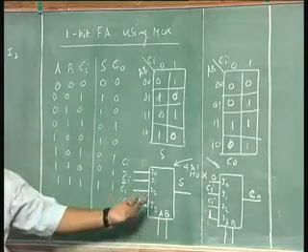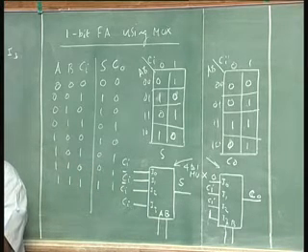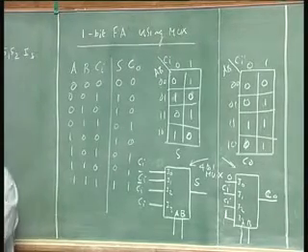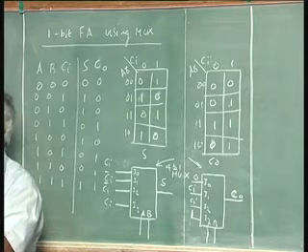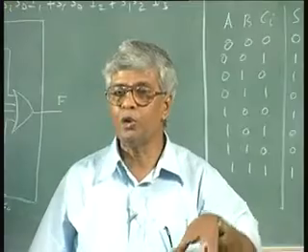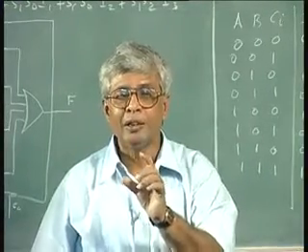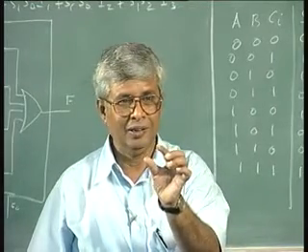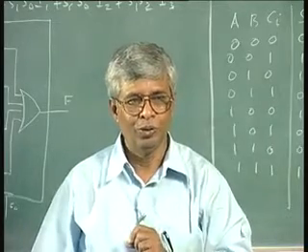So with 2 4-to-1 muxes, I got my full adder. And the beauty of the whole thing is, as I was just telling you, these things come as packages. 4 2-input AND gates come as a package. 4 2-input NAND gates come as a package. 6 inverters come as a package. Likewise, 2 4-input multiplexers come as a single package. It means this: I can go and find a 4-input mux individually. When I go and buy a 4-to-1 mux, I will always get 2 in one package.